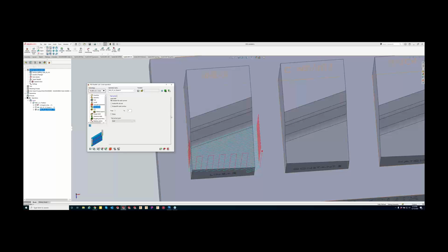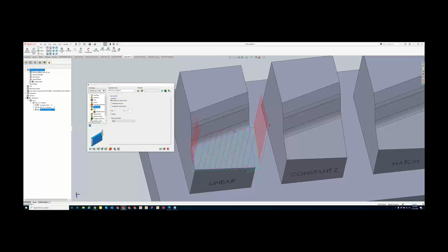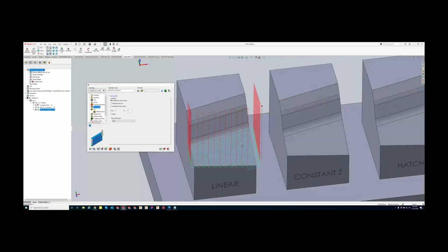Now, tool control. Now we talked about gouging into our part, going a little bit deeper in the levels area. I kind of like to use this one. Think of this as your levels. All right, so maybe I want to go a little bit deeper, the entire tool path. I would just want to drop down everything. And if we had this tool path involved right here, if we did a drive surface offset, it would push everything in there. Where if we do the shift right here, we're basically shifting the tool path down.